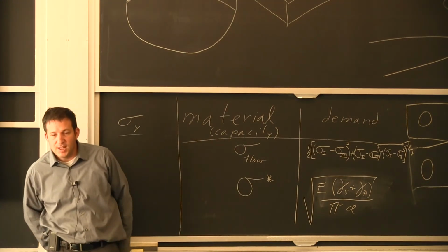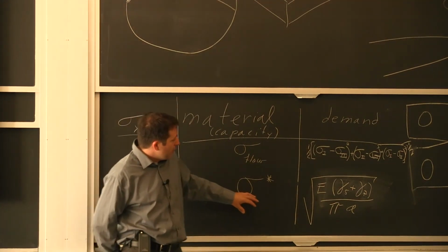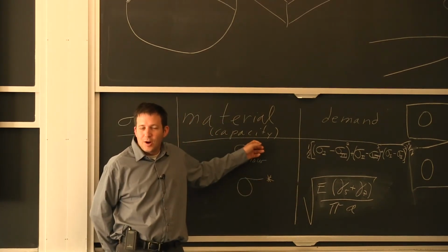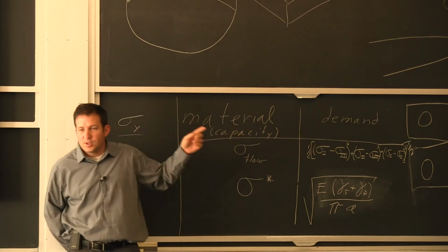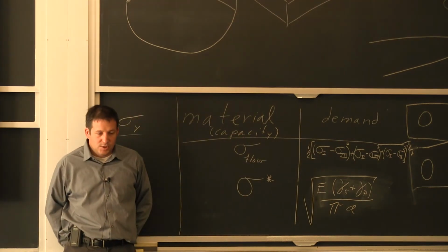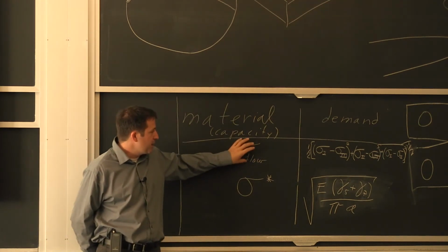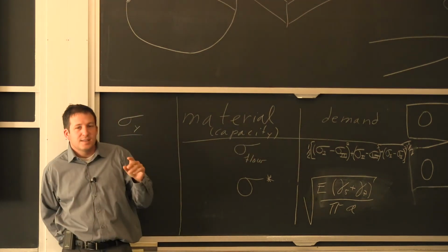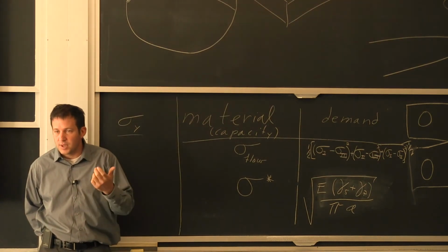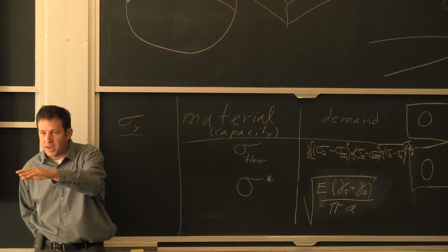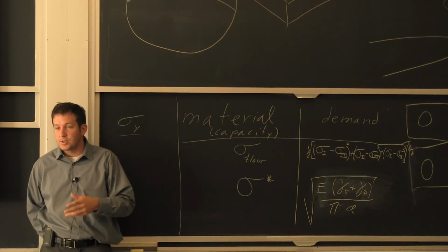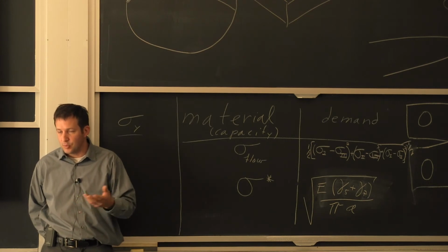If you can inhibit all the slow cracking and the brittle fracture, you are in a situation where the behavior is the best, the most predictable. As soon as you get away from this very ductile behavior, it's difficult, because now it's not going to show signs of distress. It's only going to form little cracks, and if you don't have ways to detect them, you can have a sudden failure without any pre-sign.